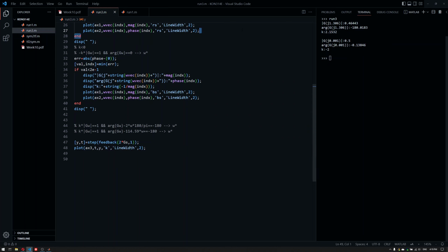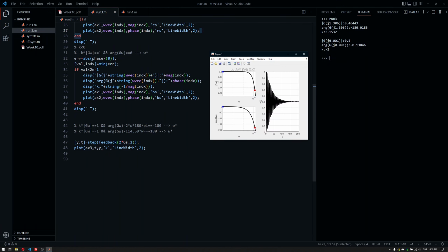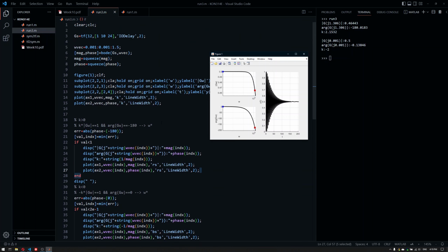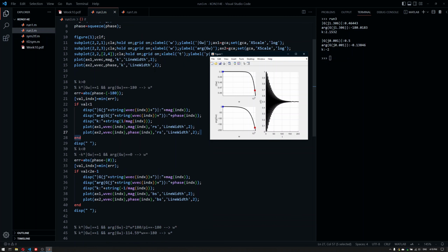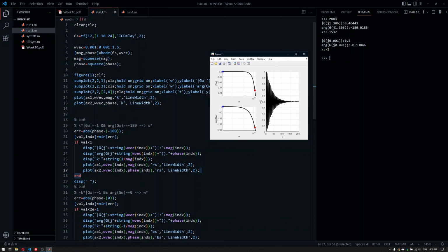Another note for classical exams: we know that the magnitude plot is not affected by the delay part here. So sometimes it's quite possible that in the exams you get a Bode plot of the minimum phase part, without the delay effect, and then you're asked to take that into consideration.